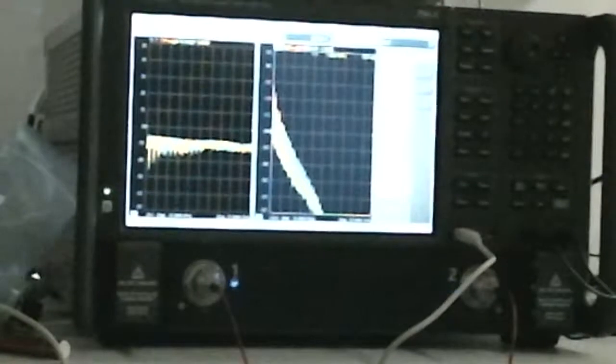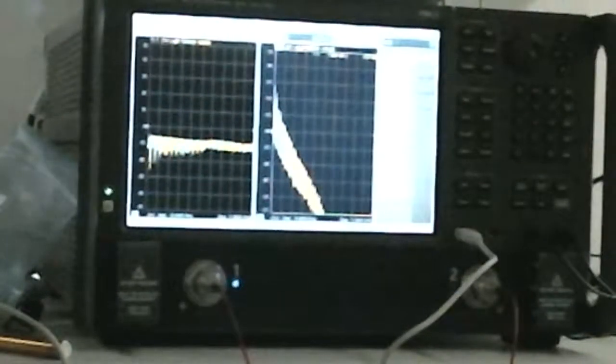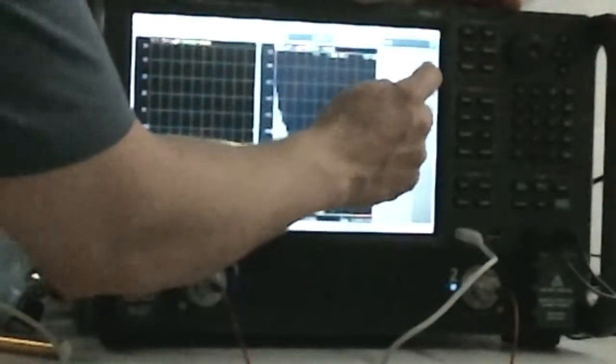You can measure the DC power at the same time, and take this gain and divide it by the DC power consumption, or the output power. So you can go under the math functionality here, under analysis. There's something called equation editor. You can launch this, and you can use this to select a full equation.